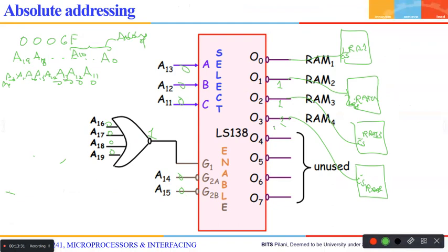The problem comes when the microprocessor is 16-bit, capable of taking 16-bit data, but your memory is capable of giving only 8-bit data. During that time, we have to completely modify our entire design. Instead of using one memory chip, we have to read from two memory chips, because the microprocessor can read 16 bits of data.